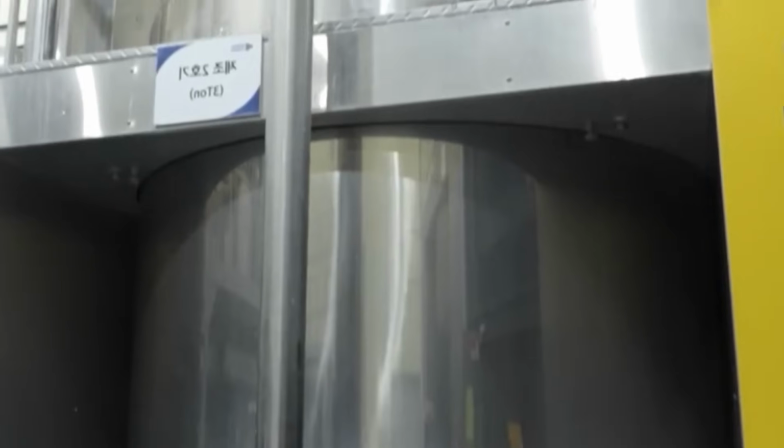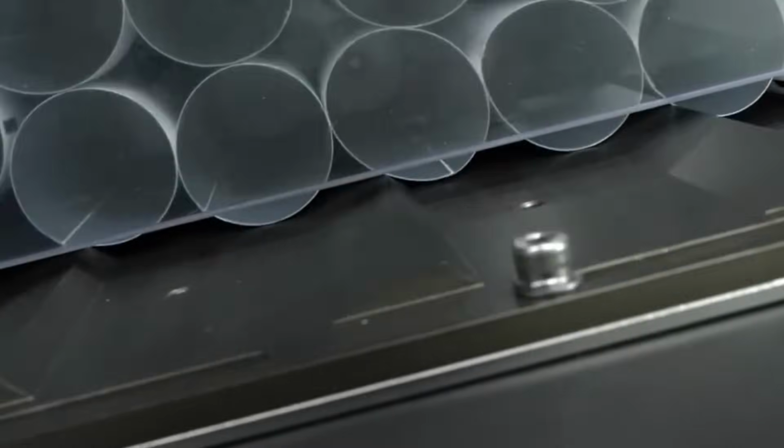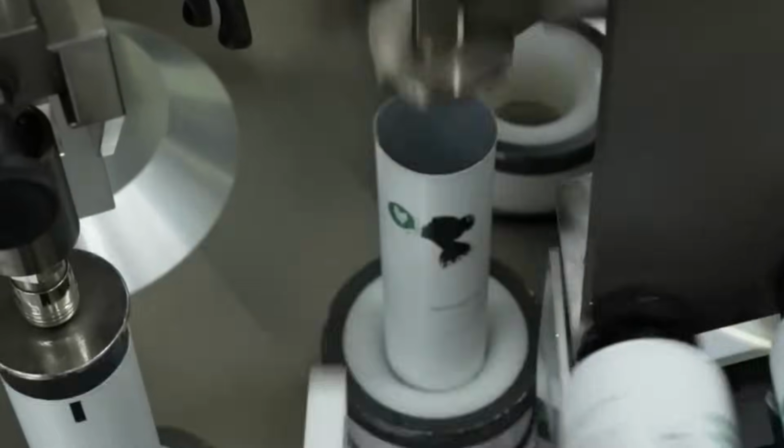Once all materials are loaded, the main batch undergoes high shear mixing. The vessel uses multi-stage impellers, typically a bottom-mounted anchor blade for macro movement and a rotor-stator head for localized dispersion. Mix time ranges from 30 to 45 minutes. Viscosity is continuously measured via in-tank torque sensors and correlated to predefined set points.